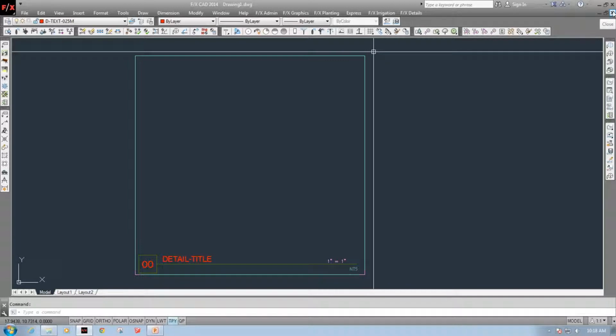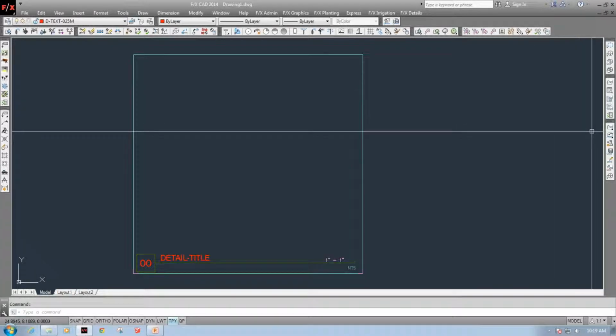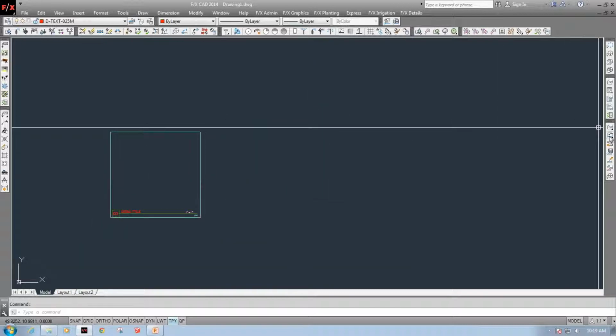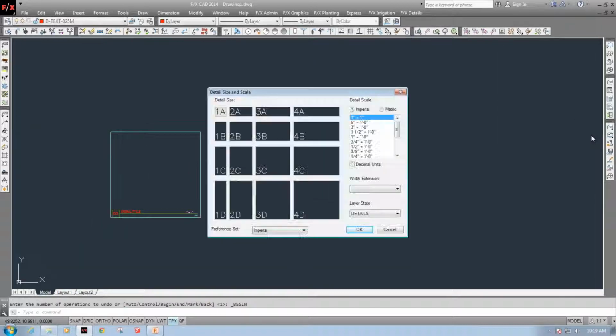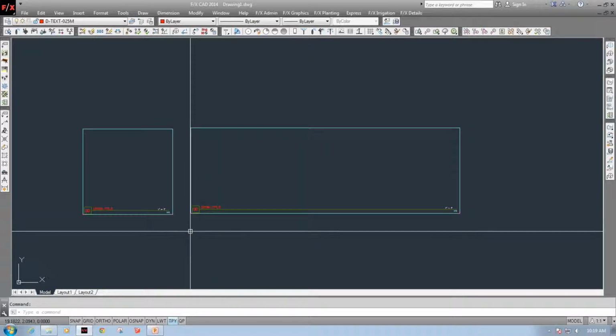And then with that, Brian, also if people notice the width and height setting there, that's why we keep those little non-plot tick marks in that title block, so that if you do want to change the width or height of your frame, you have those non-plot marks to help with doing that. Correct, yeah. So you'll notice that title block will still take effect if I choose a different size.